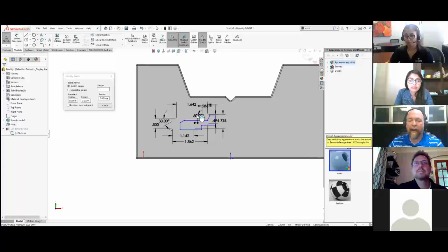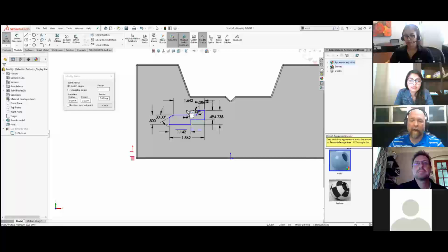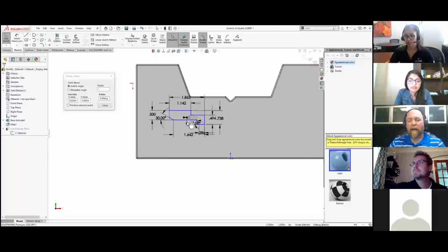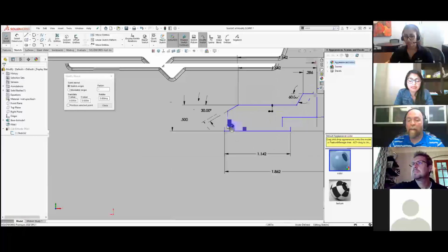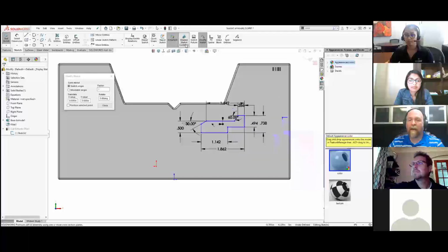Again, you can left drag that, but the left drag was available the whole time. So whether I'm needing to mirror that or completely move it around, not have to worry about it, yeah, if you have a completely closed contour, you can drag it. But remember, mine wasn't closed. I had a little construction geometry here, so I don't have that shaded sketch to just click and drag. So it's a little more difficult.